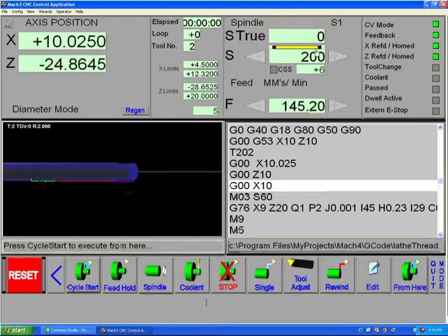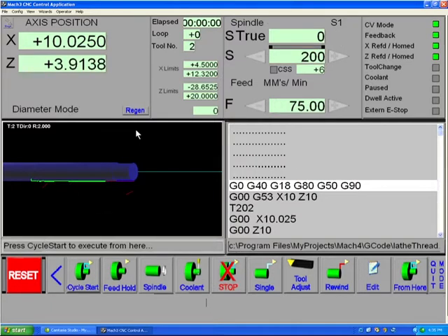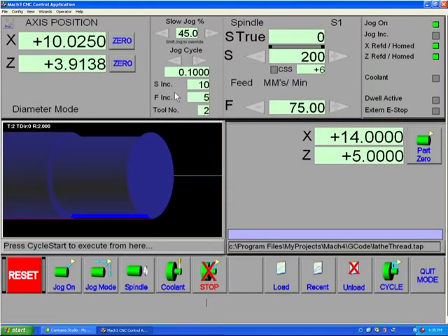You'll notice in this case I have the spindle on, but I have no spindle true RPM reading. That's because I don't have the machine hooked up at the moment to it, and I'm not feeding a spindle pulse into the machine. I'm going to stop this. Tools are selected in Mach 3 with MDI lines or by typing into a tool selector. Normally, however, you will select them with an MDI line or in G-code, of course. T01 would mean tool 1, and the following two numbers would mean offset number 1.